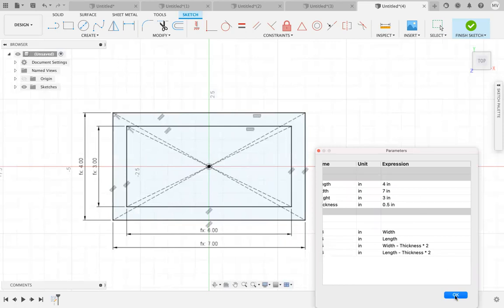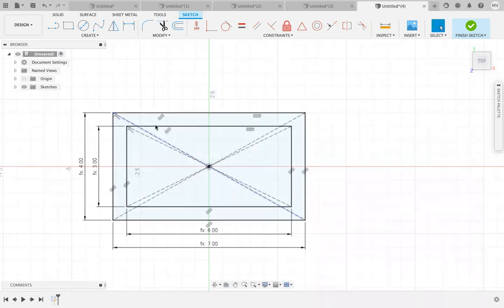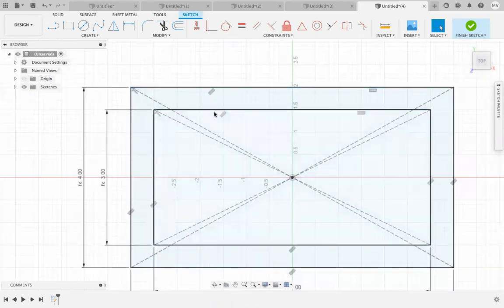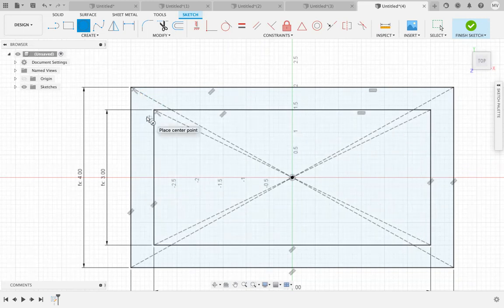So we're really close. The next step is I need to place the holes for the top corners. A lot of people start a whole new sketch. There's no need to. If you can put everything in a single sketch, it's cleaner. It's better for most of your designs. You have one place where everything is located, and if you have to change anything, you know where it is. So let's place that circle right in the corner. Now, there's nothing really for me to click on. I don't want it stuck on this line, right? I need to put something there to align to.